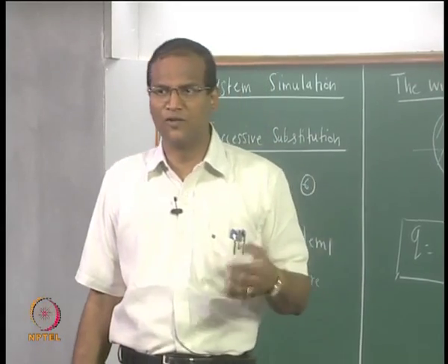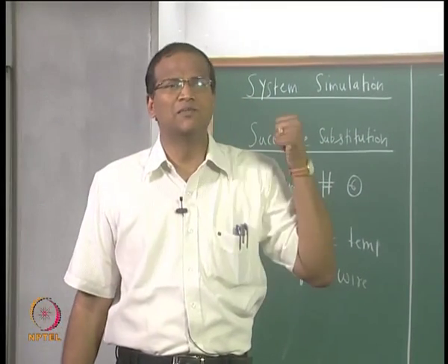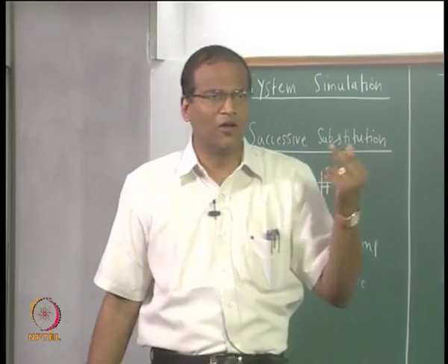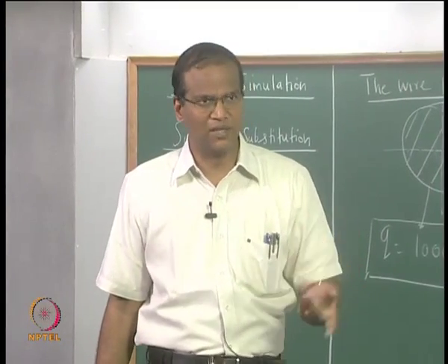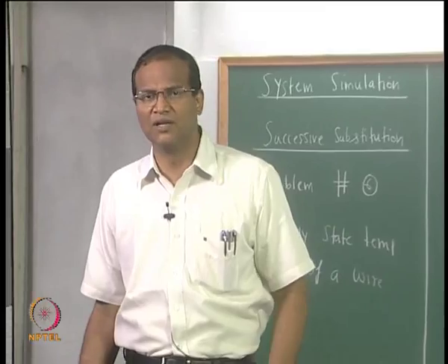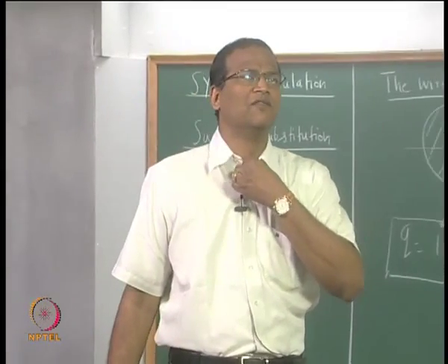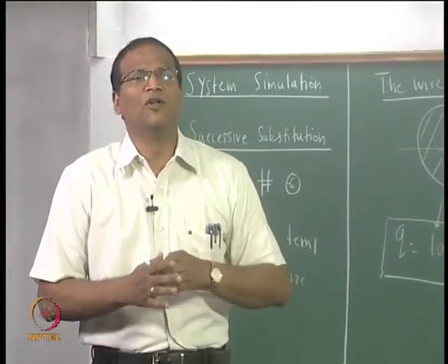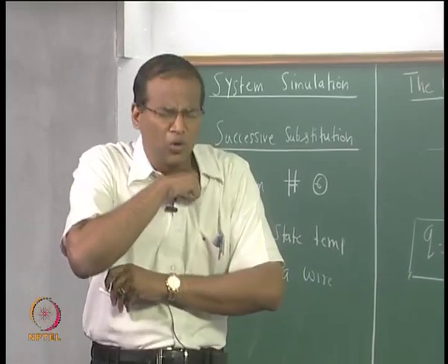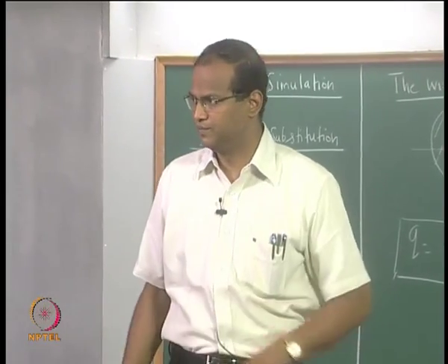There is no epsilon in so far as the surroundings is concerned. This problem can be solved either using the network theory or using the radiosity irradiation method. I teach only the radiosity irradiation method. Using the radiosity irradiation method, in 15 minutes you can show that this is the formula you get for a small body in a large enclosure.